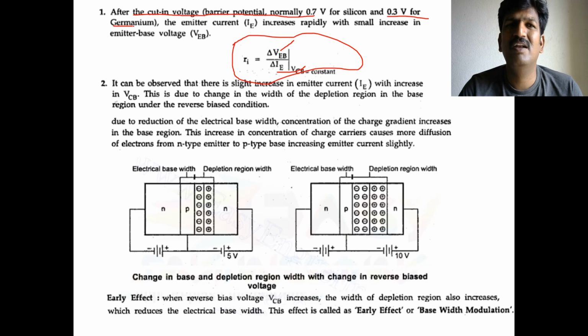What are silicon and germanium here? Silicon is the semiconductor material used to form a junction, to manufacture p-type and n-type material. If you design the whole transistor with germanium material, then the minimum supply voltage is 0.3 volts to make that semiconductor device or junction diode conduct.